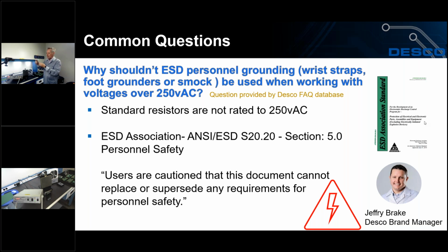So now I have a high resist situation. That tells me that I'm above that resistance. However, in your touch tester also, you have a setting in there that makes sure you don't go below 750,000 ohms also. So our tester has a delay in it. When I remove my wrist strap, it allows me to park my cord on it so I don't get false alarms. This particular cord that I just plugged into it, you'll see it's got a red head on it.